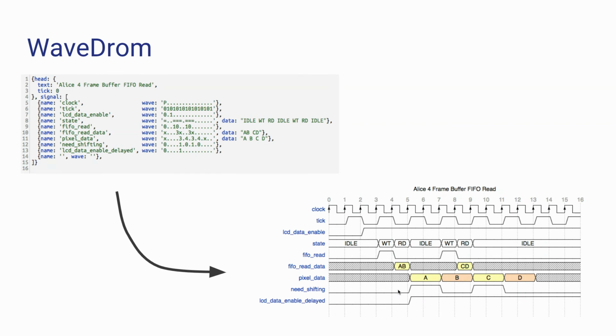And it was super useful to see here, for example, I don't know if you can see these dashed lines, they correspond to the clock. This up arrow here is the positive edge of the clock. So for example, if I set FIFO read to on at this clock, afterward you see the rising thing. And that was super useful for me visually to truly get into my head that it's after the clock that it goes up and not before, and it's readable here. And if it's changed back, then it goes back. I don't know if you can see, no, not so much?